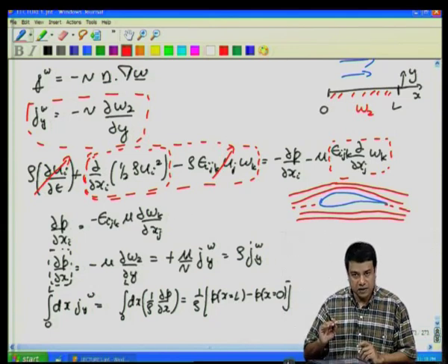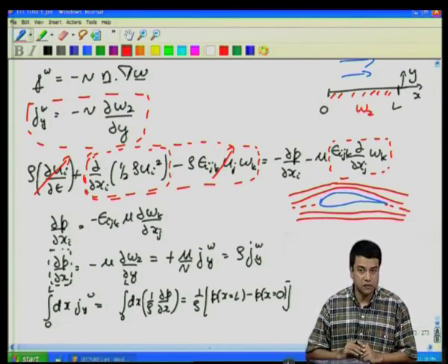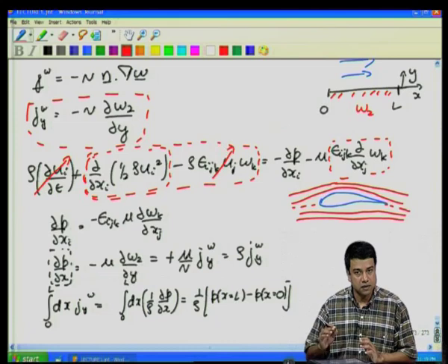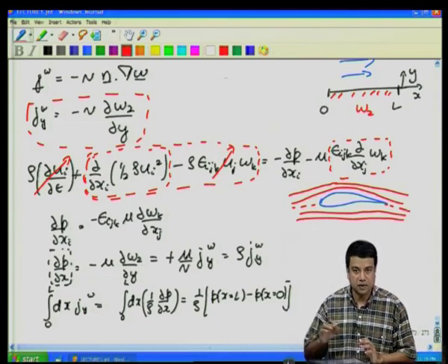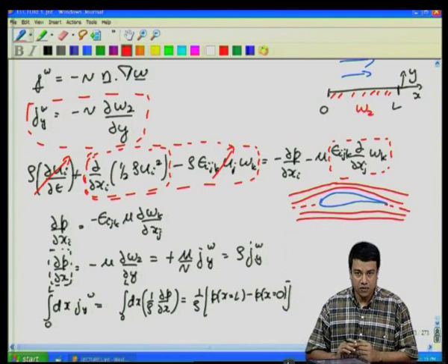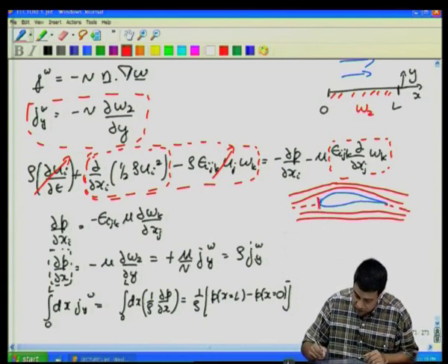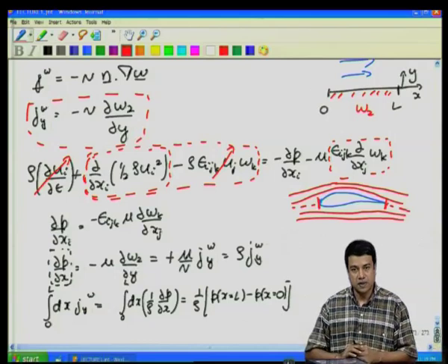When the flow accelerates, the pressure of course decreases, because p = -½ρu² + p₀. The pressure initially decreases and then as the flow decelerates, the pressure increases again. However, you know that the pressure at these two ends has to be the same because both ends are open to the atmosphere.